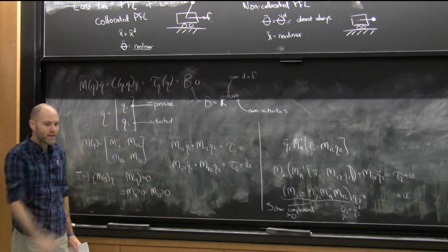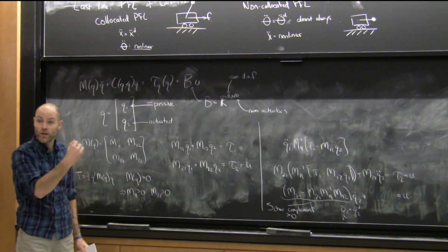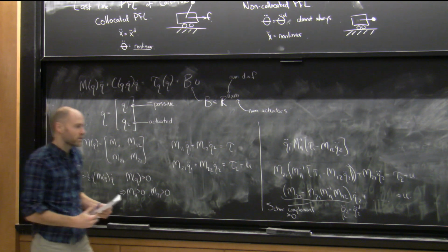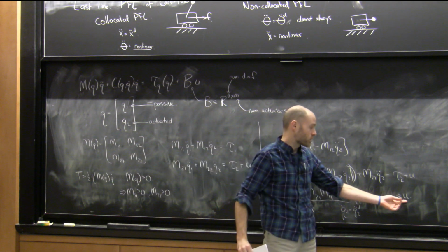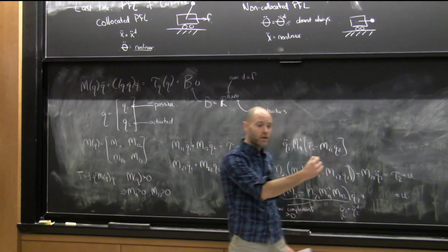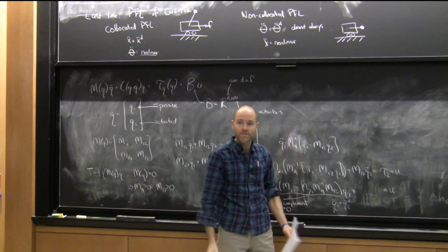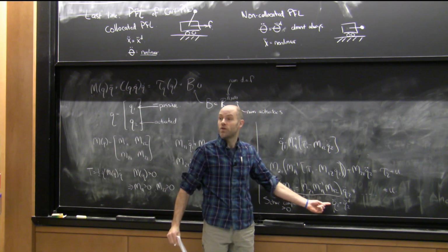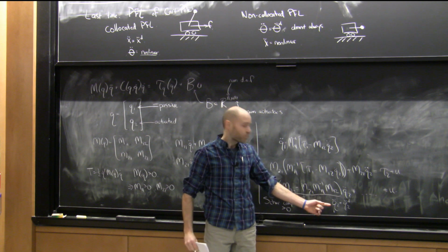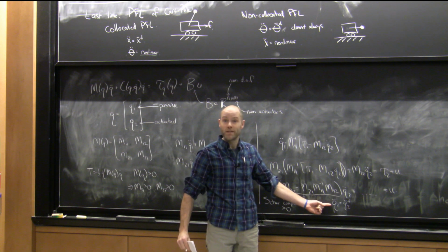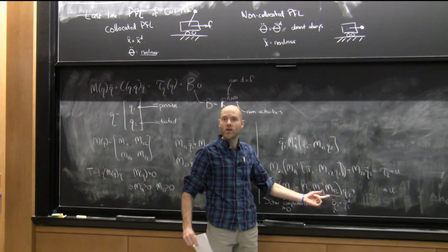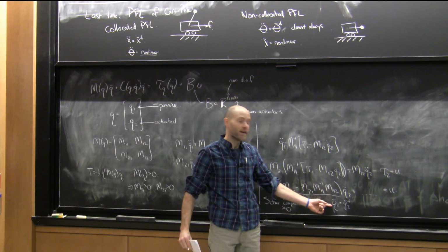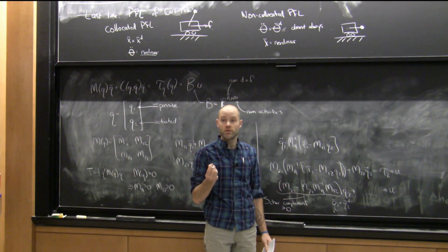I can look at the effect of my other joints, apply enough torque, okay? I've not given myself any torque limits, so I'm assuming I can command the sufficient torque to subtract out what all the other passive joints are doing to my actuated joints, and make my actuated joints do the thing I want, okay? In practice, you could also just do this by putting a really big feedback gain on something, right? You could just overpower it with high gain feedback. But the model-based way is you look at what all those other forces are, you cancel them out exactly, and you're left with perfect control of the places where you have motors.